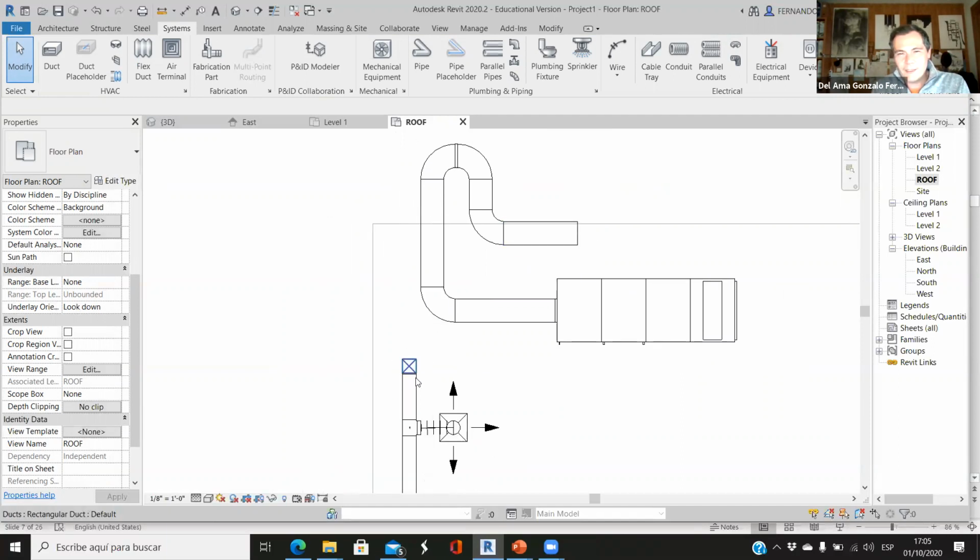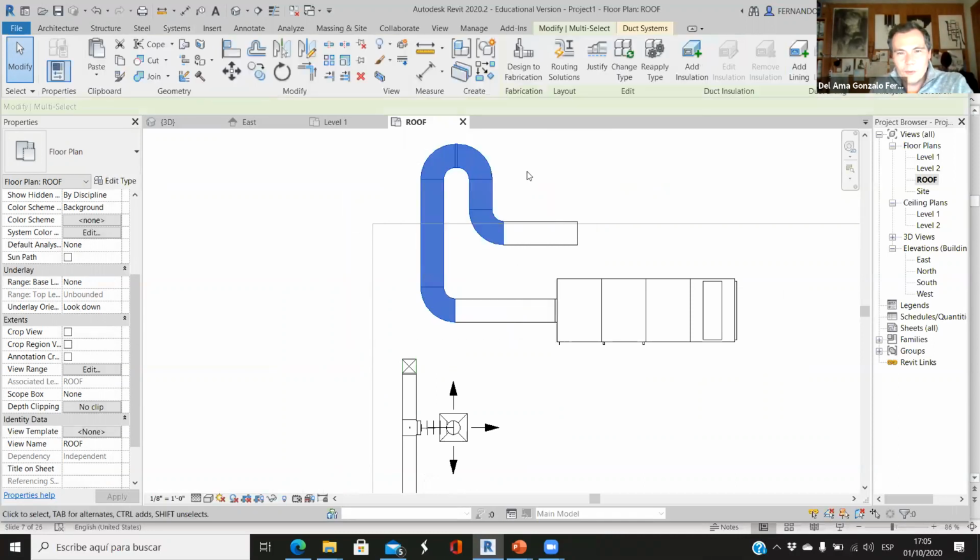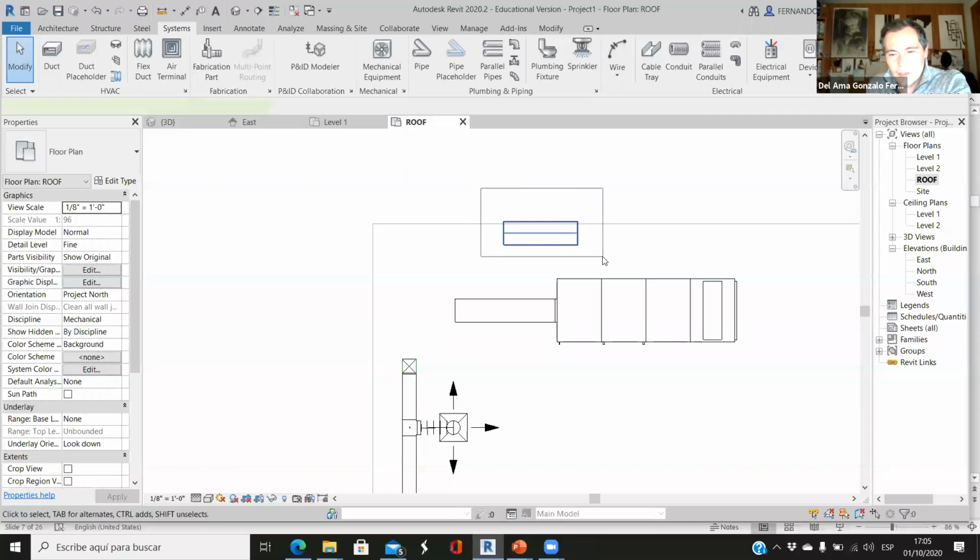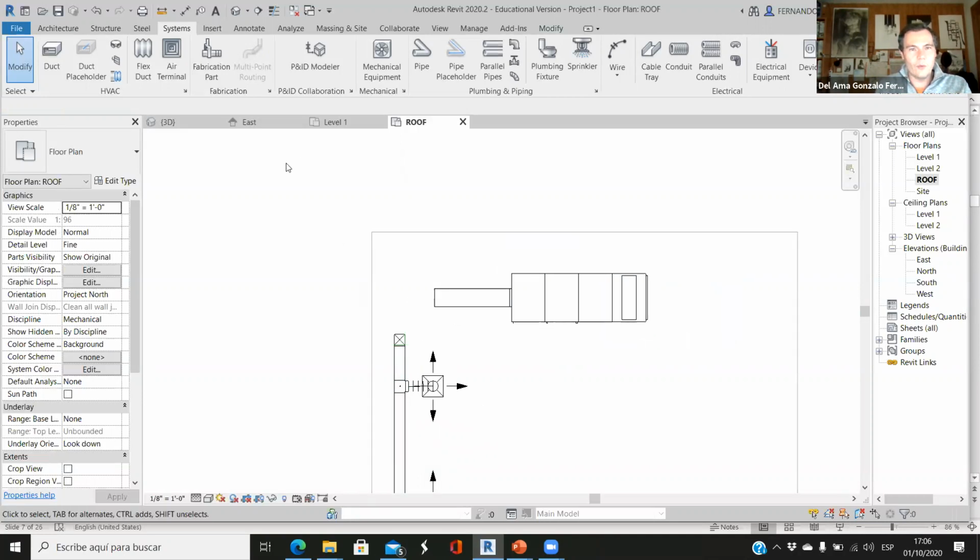It's not going well, because I'm forcing this, so I have an elbow, and then I have to go down with another elbow, and I don't have enough space. Usually these things work better when we simplify things. So the fewer the fittings, the better. Why do we have a horizontal elbow and then a vertical elbow? What if I have just a vertical elbow there? It will be easier, it will be more effective, and it will be easier for Revit and for the workers that are working with this. So I have to change that design.